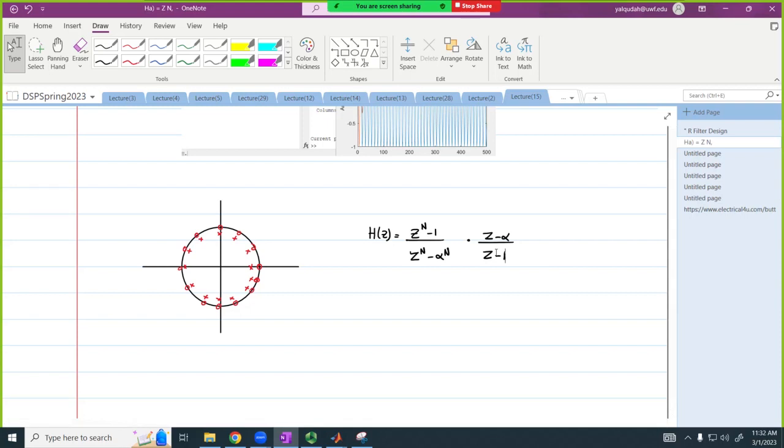Okay. So what we're saying, everybody understood the comb filter and how it works. What we said is, what if I want to remove this pole and this 0? I want the filter to be such that it removes all these harmonics, but keeps the DC. When omega is 0, I don't want to filter anything. And we said, if I want to remove these, this corresponds to z minus 1. That's why I have a 0 here.